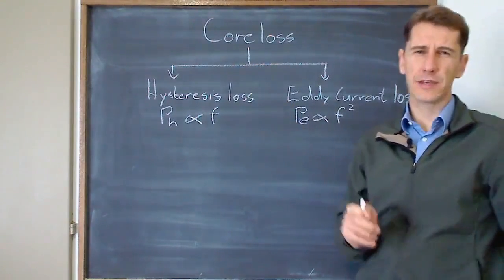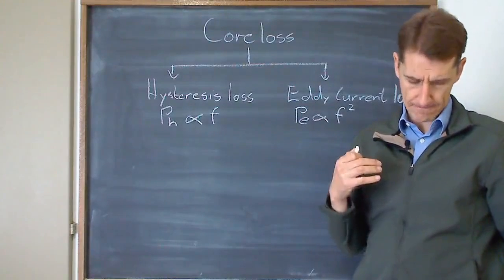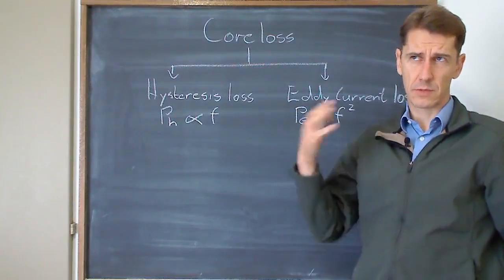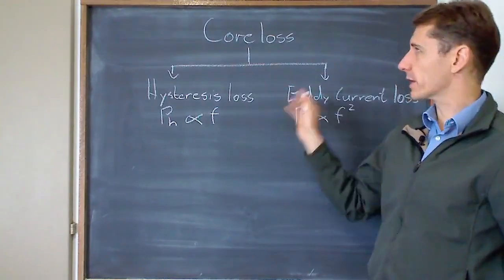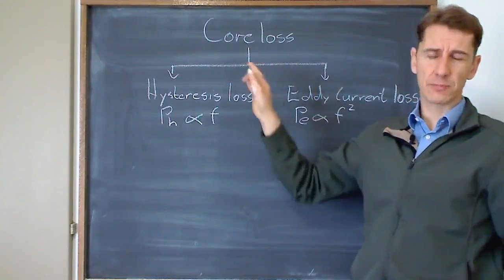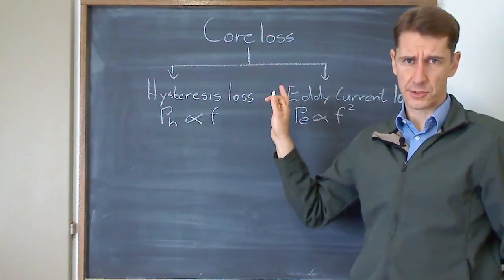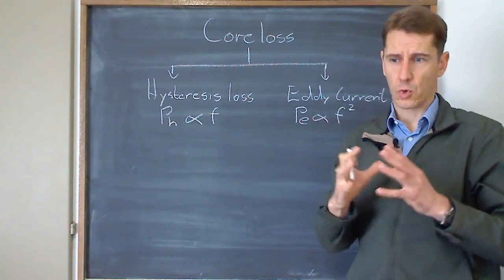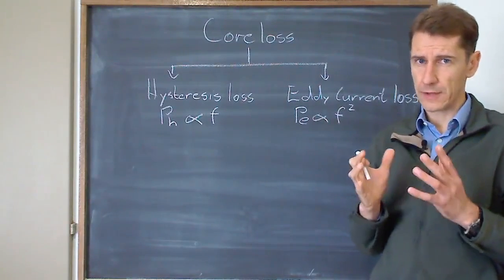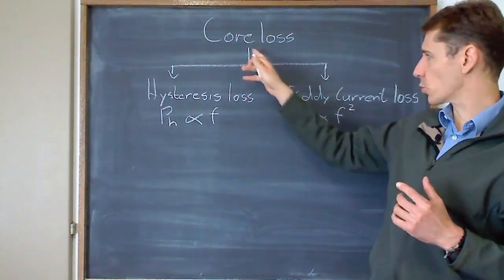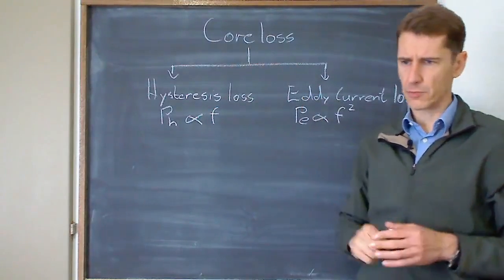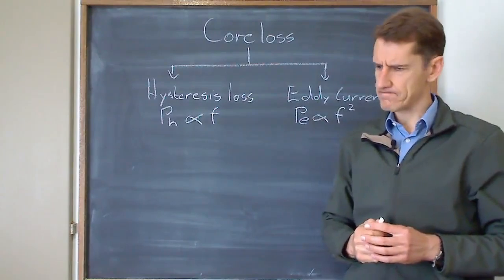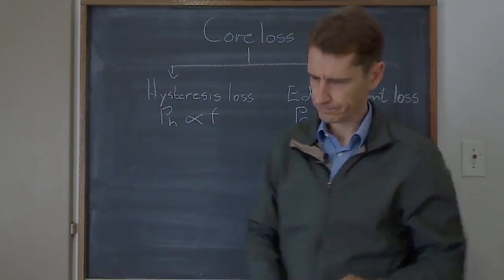And when we get to induction motors and transformers, actually not next lecture, the lecture after that, we're going to come back to this concept of core losses. All right, so hysteresis and eddy currents combined form your core loss. All right, not like in the textbook where they equate core loss to hysteresis loss. So hopefully you made that fix. Okay, let's go back to the textbook.